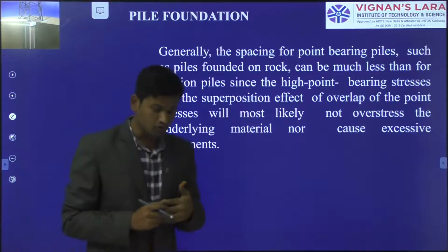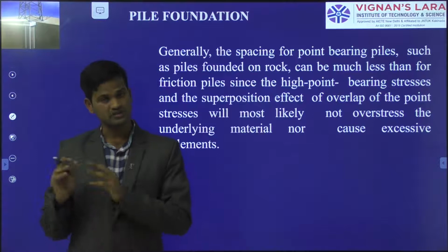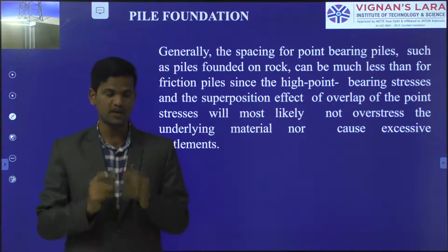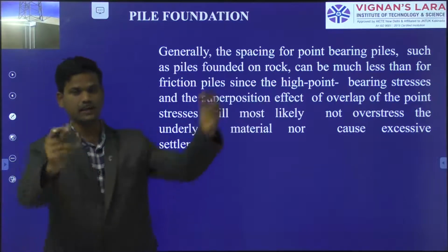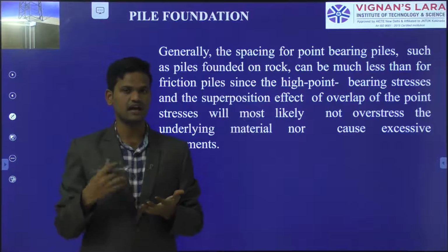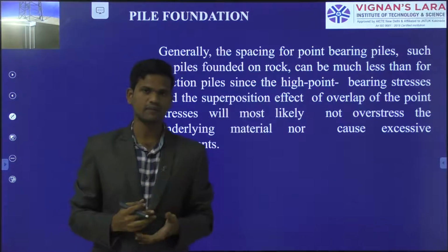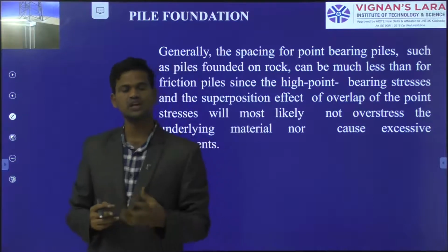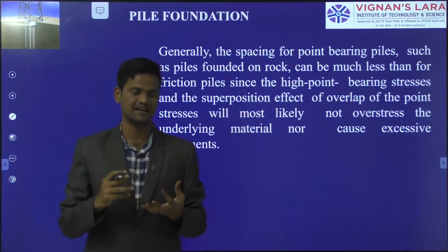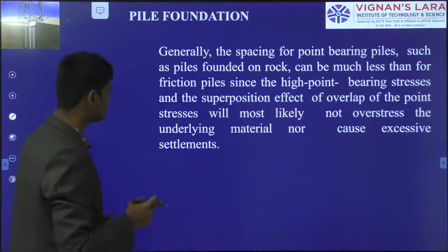That means whether you are providing the piles in very soft soil or medium to soft soil, or whether you are providing them in very hard soil, based on the load carrying capacity of the soil mass or rock mass, you can insert the number of piles. If the load carrying capacity of the soil is very low, then you can insert more piles. If the load carrying capacity of the rock or soil is high, then you can insert the minimum number of piles in a group.